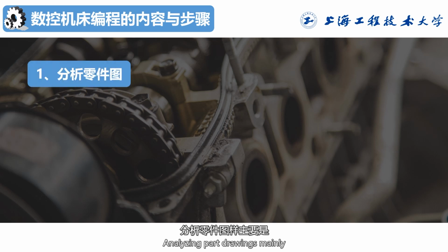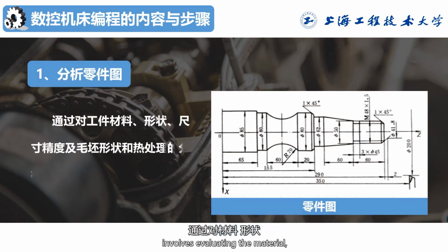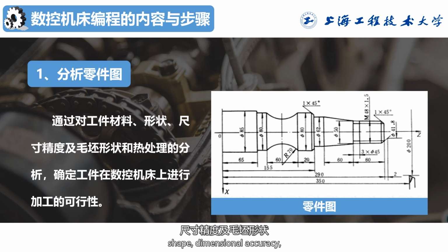Analyzing part drawings mainly involves evaluating the material, shape, dimensional accuracy, and heat treatment to determine the feasibility of machining the workpiece.